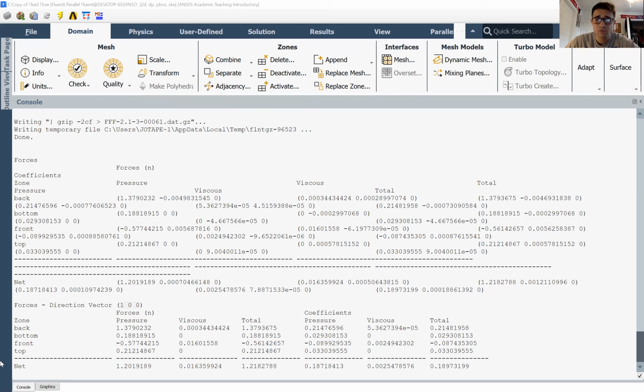Next, we have our velocity contour. We have a maximum velocity of almost 16, and our velocity is going to maximize as it comes around these edges over here. And as you can see, we do have some turbulence, which is why we have that kinetic energy contour, just so we can see the turbulence visually. We're going to have 0 velocity up along the front of the plate and along the edges of the plate due to the no slip condition. And that will complete that.